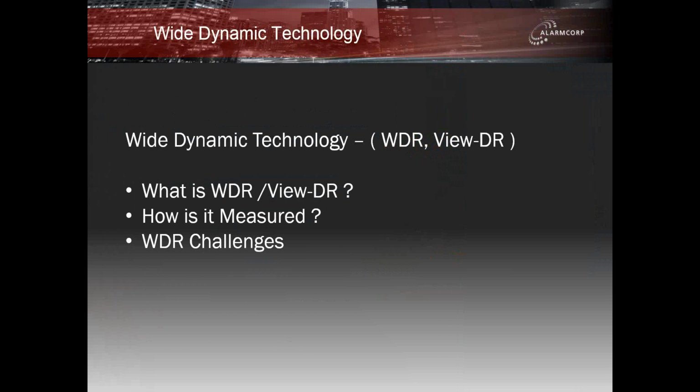It is important to understand light levels. A dark scene might be in the range of 10 to 20 lux, and a bright scene could be in excess of 1,000 lux. A WDR camera needs to be able to handle these varying light conditions. A camera needs light in order to generate an image. Whether it is natural, artificial, or an IR illuminator, they all have their challenges. Too much light washes the image out, and too little light results in a dark image. With a normal amount of light, the iris will open its shutter size to get the correct amount of light onto the sensor. A WDR camera helps compensate for these changes in light levels.